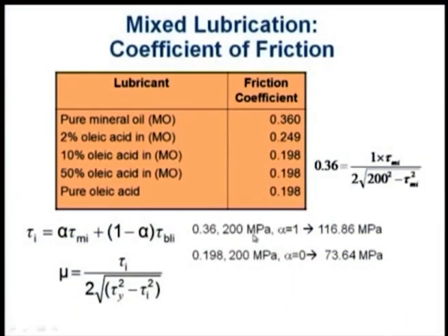Of course, if there is an excess load, even in that case, in presence of a liquid, there is a possibility of cold weld. But if there is some lubricant available, even when the load applied is high, the interface shear strength will be lower than the bulk metal shear strength, which is by and large what happens whenever we do experiments in the lab. We found interface shear strength is lower than bulk shear strength.